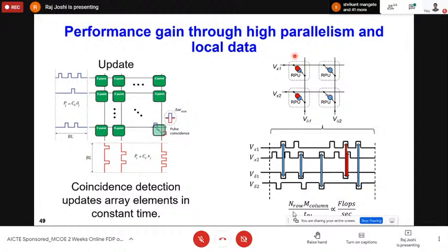That's the problem. Variability. Producing a similar result every time is difficult. That's what is happening. So you apply voltage to these memories on one side, and on the other side, since this is a crossbar, you apply another voltage, and you can change the conductance of this memory.